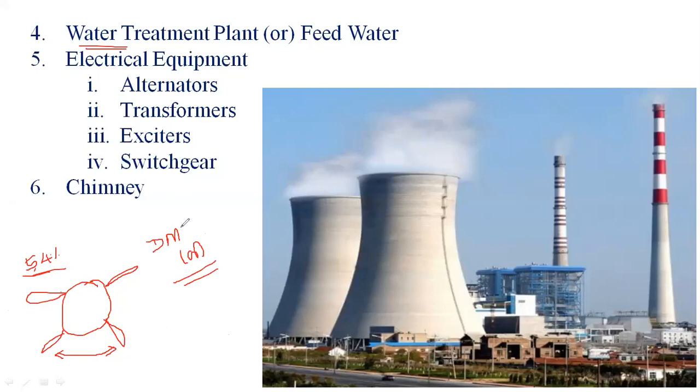But then the boiler lifetime is reduced, and both the output efficiency and the boiler efficiency drop due to corrosion and salt particles in the water. To avoid that, we use demineralized water or RO water, or simply soft water, for the boiler, to improve its lifetime and to keep the efficiency constant throughout the period.